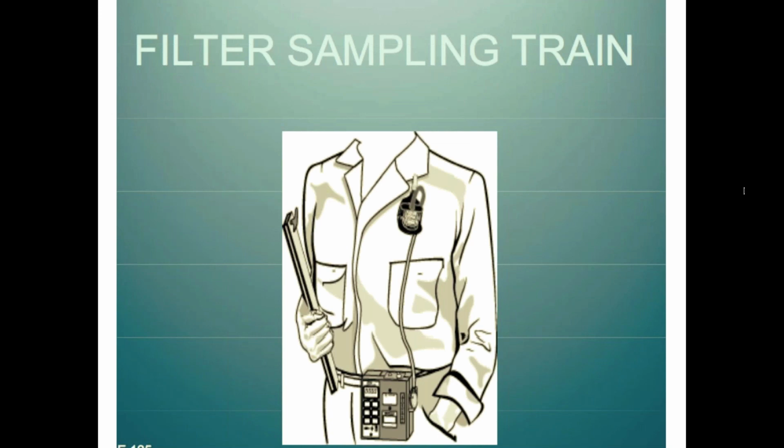So now when you measure with your calibration device, you'll actually know how much air is actually being drawn through this filter. If this was 1 liter per minute without the cassette on, now it might be 0.9 liters per minute. So you're going to want to take 3 readings, average them, and that's going to be your pre-sampling flow rate for your pump.